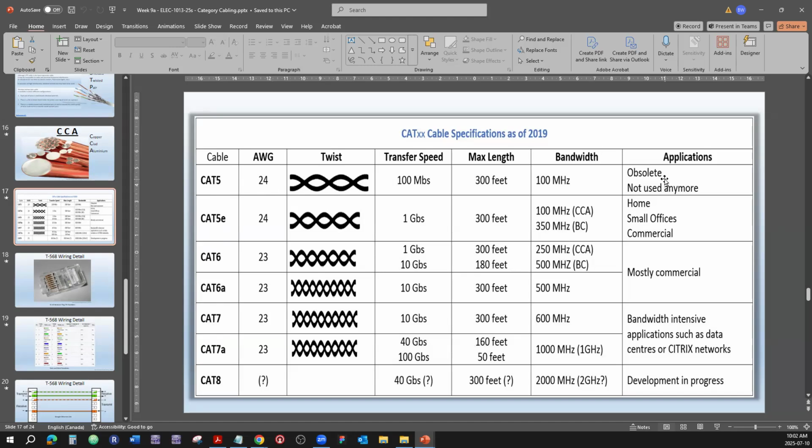And in some cases, Cat5 is not going to, as they say, cut the mustard. Because in some cases, and I'm not going to say what, some devices are not going to work on Cat5. Cat5e will be the minimum for certain devices. So when you are retrofitting some equipment or installing new equipment, you got to make sure that the wiring that the client has currently at the time that you're doing it, that the client has Cat5e wires.